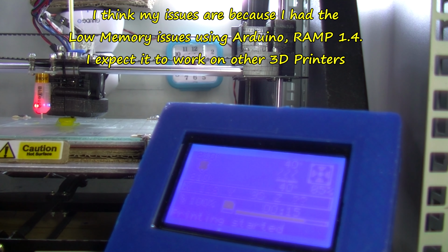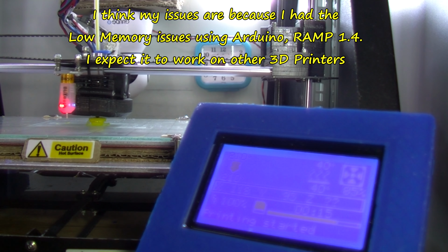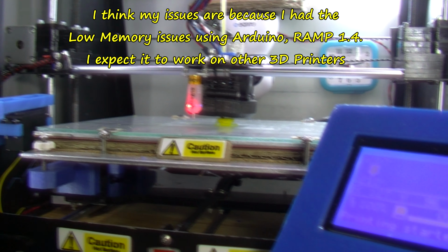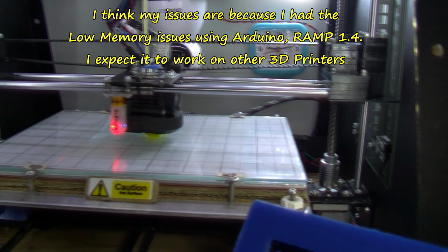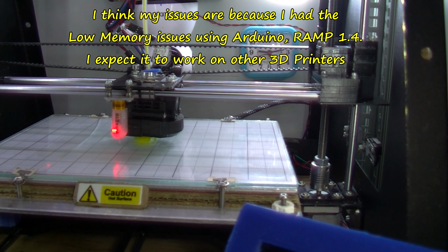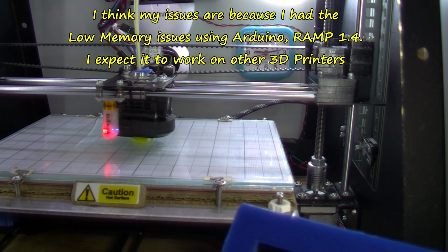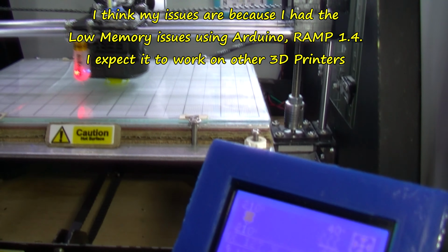Let's have a look at this again. It'll be interesting to see how this print turns out. I think the Z is not moving at all. Let me move up, sorry about this. If you keep an eye on that Z threaded rod there, you'll see that it's not turning at all. Well, that sounds like it's finishing off. I can normally hear the noise of it finishing off, and the display is indicating that it hasn't got much more to go. Yet the Z has not gone up.